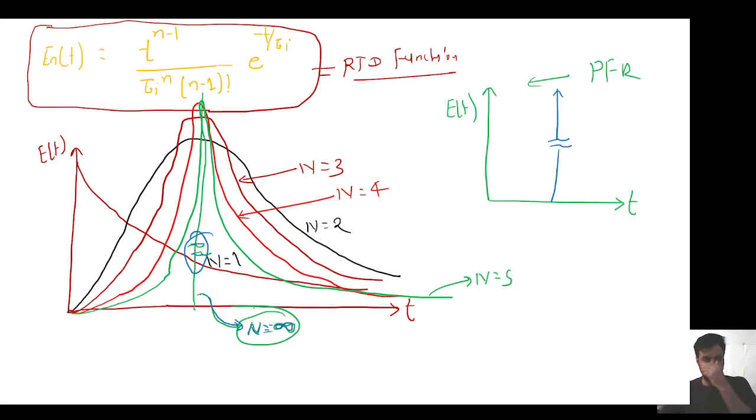So the plot will be like this. So can I say from the plot that n CSTRs having equal volume connected in series will work like a single PFR. Are you getting? So this is the objective of this session, that when we connect n CSTRs having the same volume in series, they will work as a PFR. Okay, so this was the objective of this session.